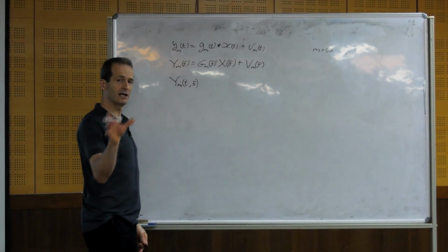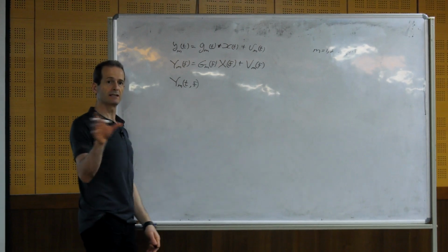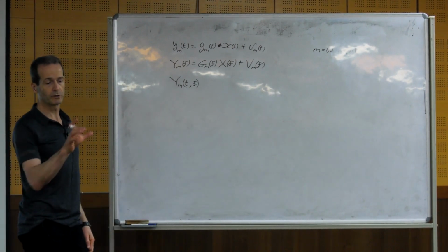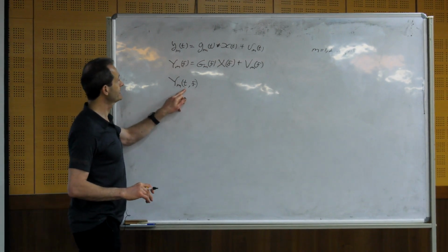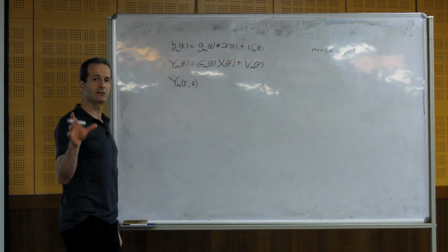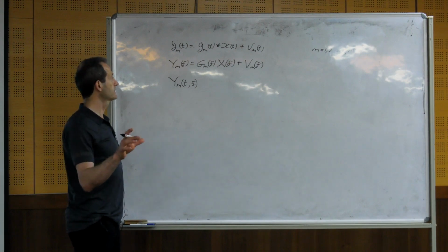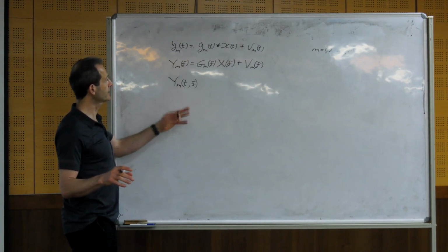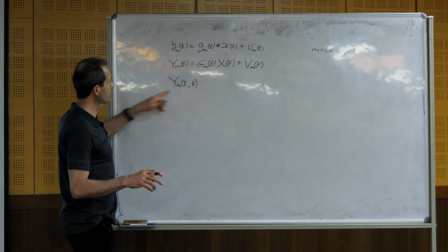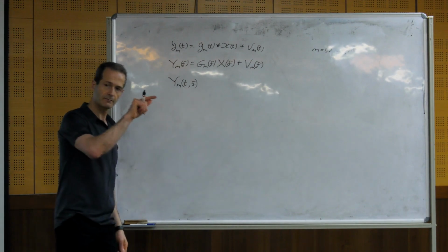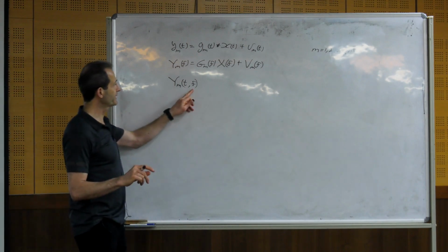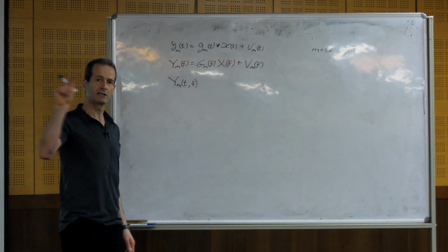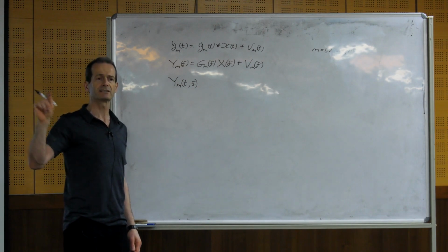And then we have some jump, we call it the hop, between windows. So this is the index of the position of the time window. So for each frequency, we get samples. Even if we fix the frequency, we get samples along time, or the index of the window.